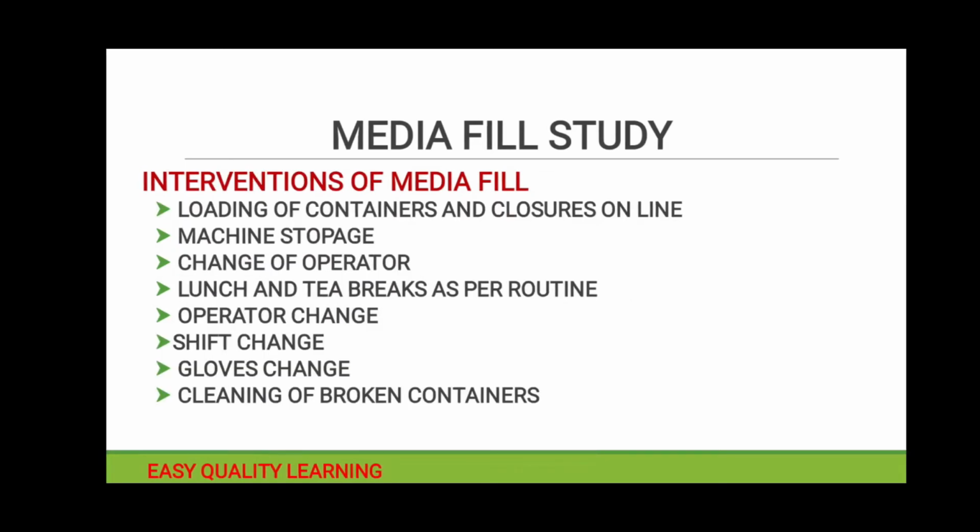Then interventions of media fill. This is a very important part of media fill: what interventions we are going to keep in media fill. Interventions are known interruptions which we keep in media fill, because these interruptions generally happen in our routine commercial production lines. Our intent is that it should not happen that any of the interventions we are not simulating in our media fill activity gives some adverse impact on our commercial production.